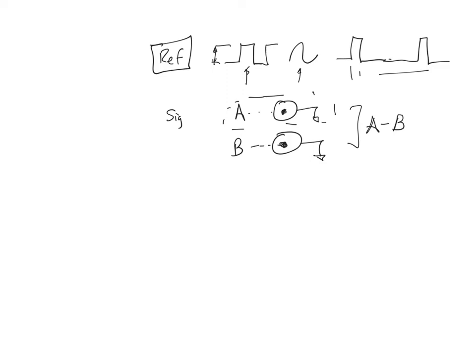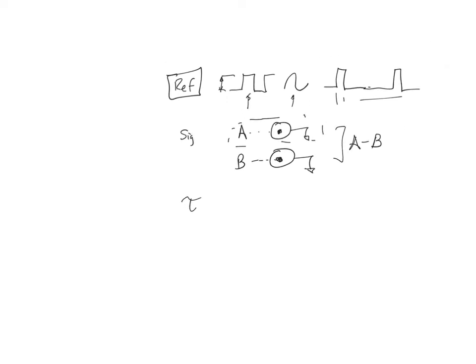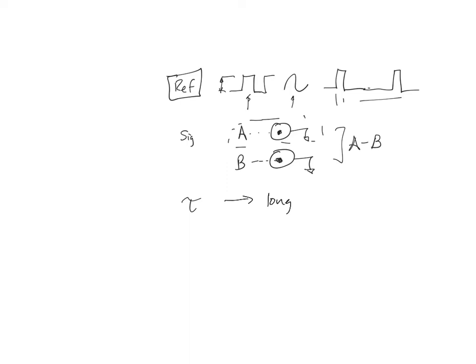And then finally, you're going to set the tau. Well, not finally. You're going to set the tau such that tau is long compared to the period. So I'll write that as long compared to 1 over the frequency that you're chopping at. So if you have a kilohertz signal, the period's a millisecond, and you want to make tau long compared to that, but hopefully short compared to the time that you can stand to wait for the output to change.